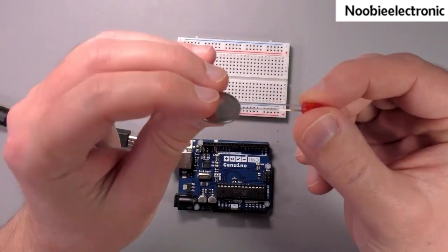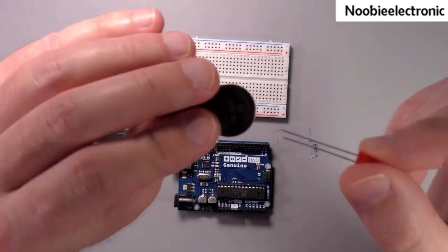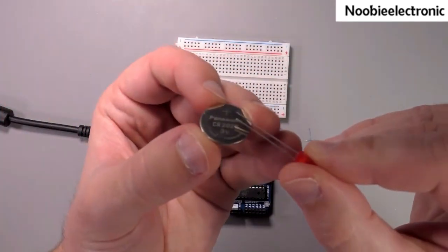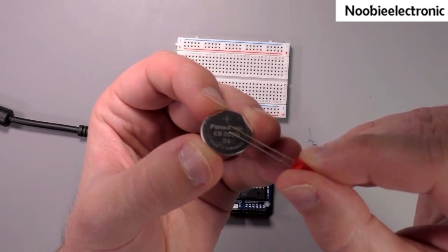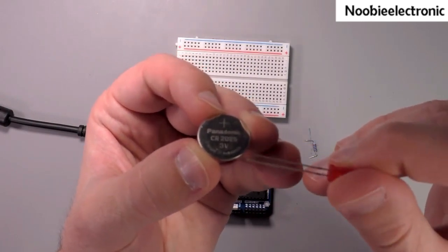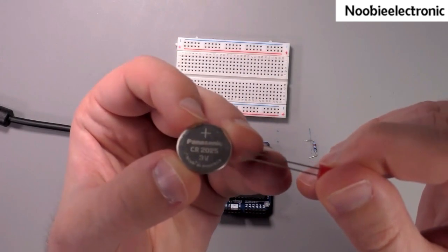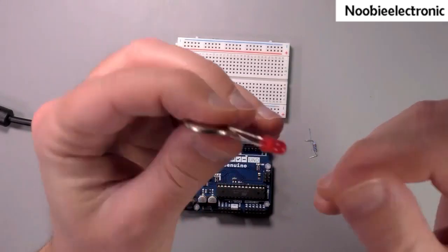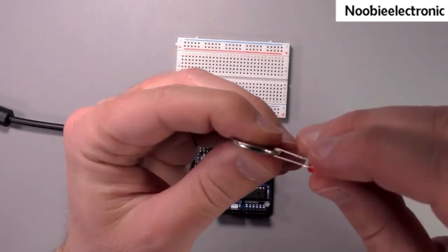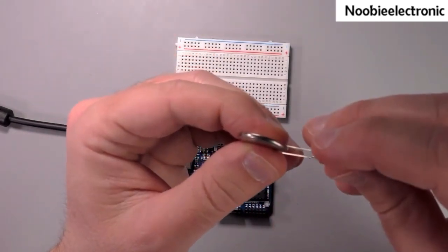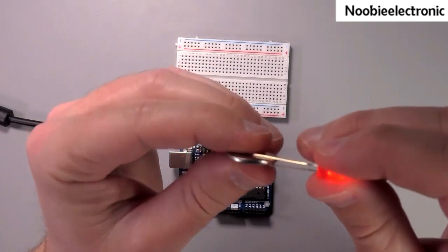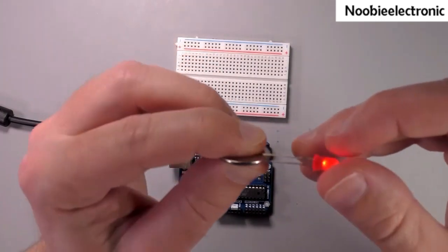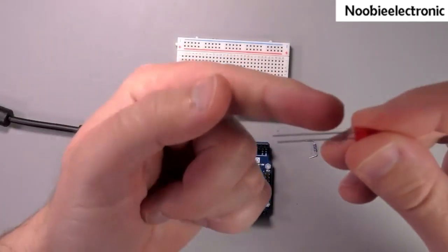And it's because I connected the long pin of the LED to the side of the battery with a plus sign. You can see that here, plus sign means positive side of the battery. If I connect the LED in the other way around, so short pin to the positive side of the battery, you'll see that it doesn't work. And this is how you can tell which pin of an LED is positive or anode and which one is negative or cathode.